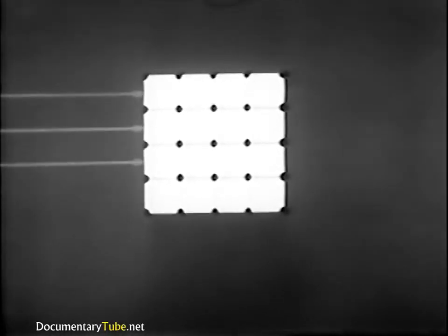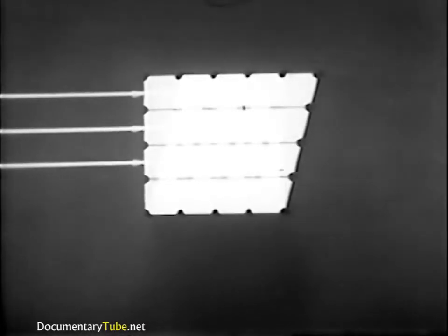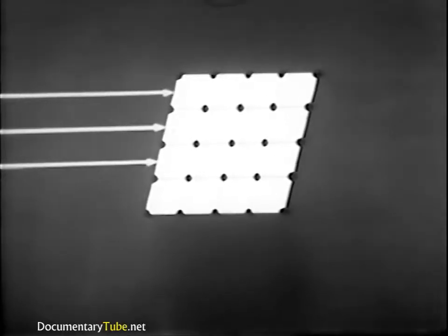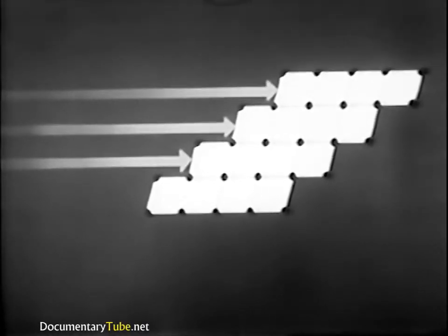The second type, plastic deformation, occurs when the applied force is increased beyond the elastic limit of the crystal. The space lattice yields. In the process of twinning, the lattice is deformed by some fraction of an atomic spacing. In slip displacement, the blocks of atoms move an integral number of atomic spacings. When the external force is removed, the atoms are so far from their original positions that they cannot return.